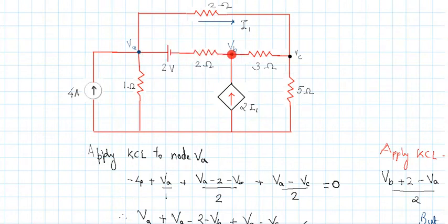It is going to be the potential difference. Since the current is an outgoing current, it means that the potential at point B is the higher potential. So VB minus VA will be there. What about this particular source? Look at the terminal now. The terminal is negative followed by positive, so it's going to be a rise in the potential.